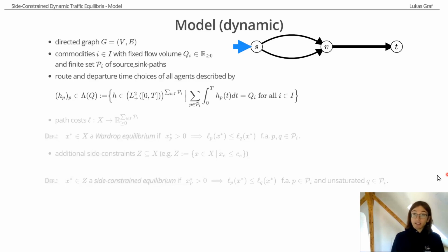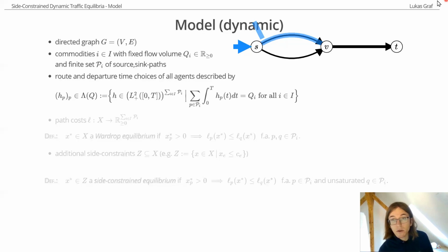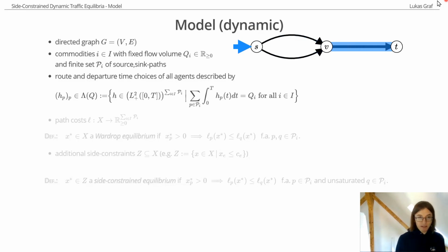And then the second component that changes is that also the flow itself through the network changes dynamically with time, right? So particles enter an edge over time, then traverse this edge taking some time. Some congestion effects may take place, modeled here as a queue. And then, of course, the inflow into certain edges may change over time. And so we have some dynamic flow here. And this dynamic flow then leads to dynamic travel costs, right? So the cost of traversing a certain edge changes over time.